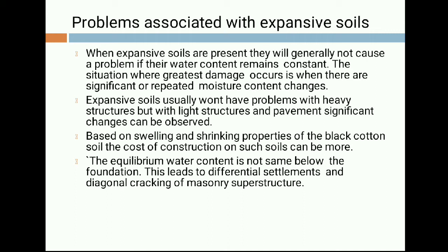The equilibrium water content is not the same below the foundation. This leads to differential settlement and diagonal cracking of masonry superstructures. Means what? This means if there is more water variation below the underground level, that can lead to differential settlement and diagonal cracking of the interior wall as well as the exterior wall, because the water content below the ground is not equal at all points around the same structure.